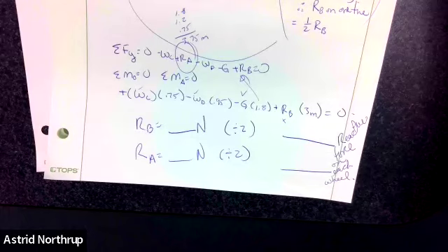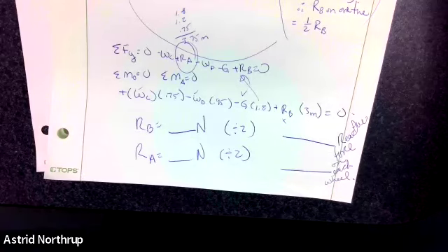Yeah, first of all, we're multiplying by 0.75 times W_C, the weight of the crate at C, times the distance between, I decided to take the moments about point A. So this is the distance between C and A. So all of those distances would be distances between that load and point A. Yeah. Good question.